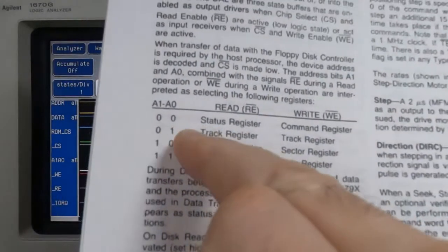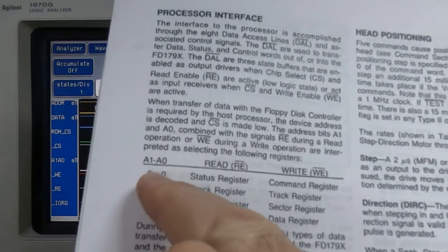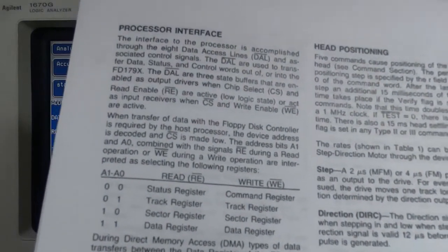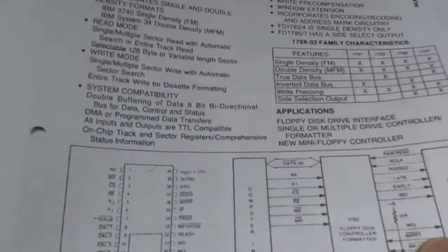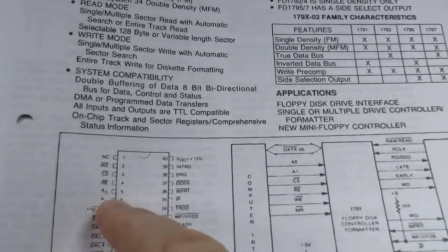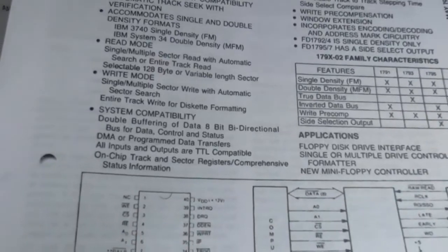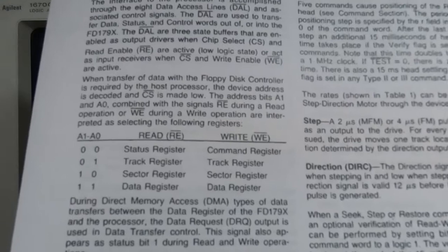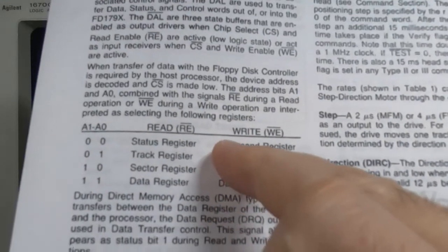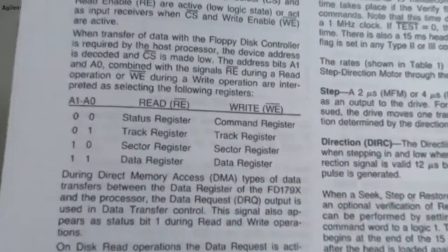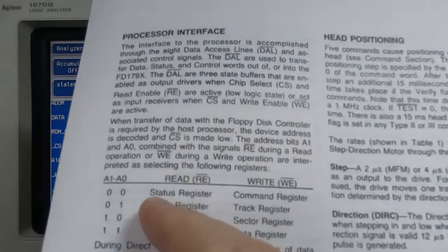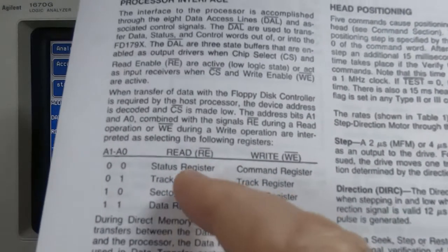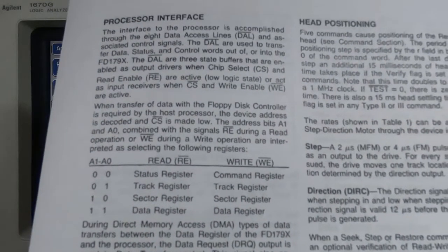So this is the table for these registers. These A0, A1 lines are the 2 lines going into the device. So that's these 2 lines, and they're used to select the 4 registers. These are connected via a buffer to the A0 and A1 lines on the Z80, so we know that these registers will be addressed in consecutive memory space. We know now that the first one is at 20 hex, so we know we're looking for 20, 21, 22 and 23 hex for these registers.